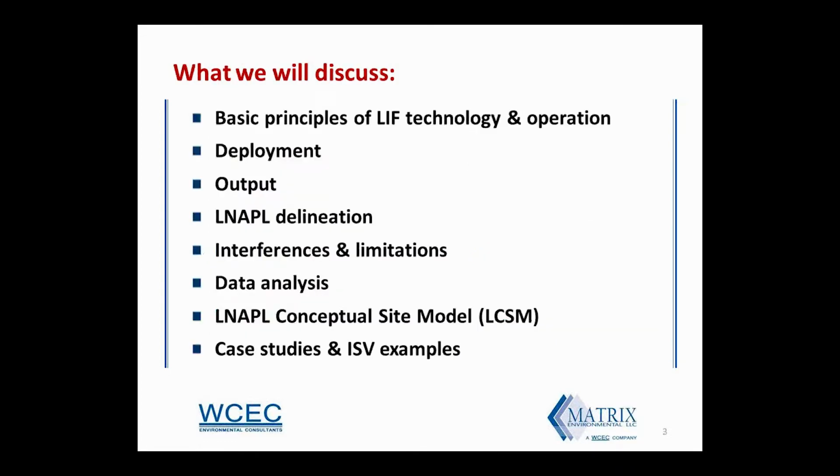Here's an overview of what we'll be discussing today. We'll go over the basic principles of the LIF technology and equipment operation. We'll show some examples of deployment of the instrument in the field. We will talk about the data output, including a review of the logs and waveforms produced by the instrument. We'll give a very brief overview of contaminant phases in the subsurface and talk about how LIF is used to delineate the non-aqueous phase liquids.